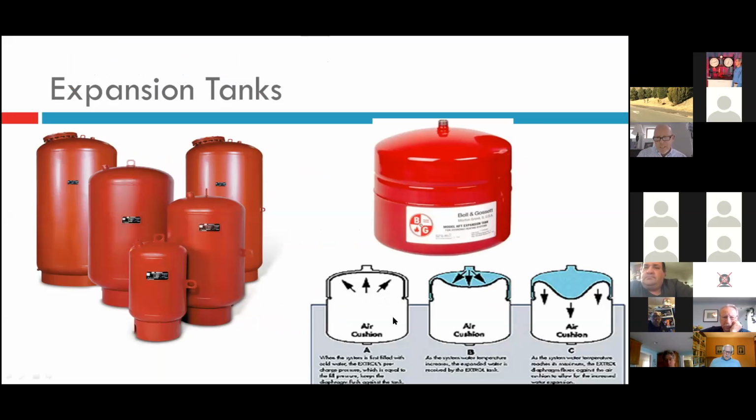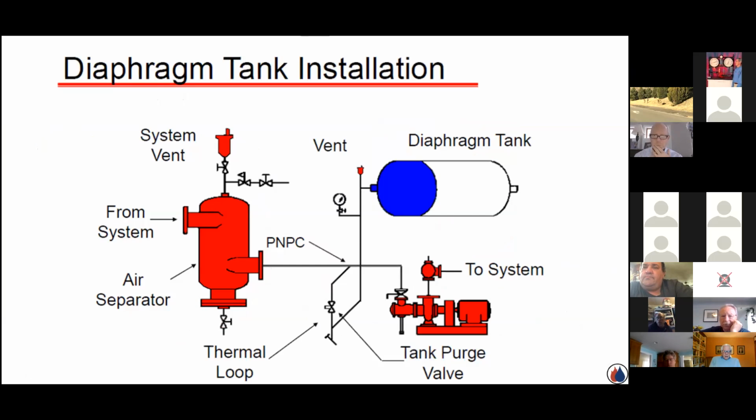What's happening here, this is a great little picture. When they're pre-charged, there is no water in them. When you attach it to a system that hasn't started the boiler, so the water's at ambient temperature, I really don't want any water in that tank, because that's how this tank is sized. It's only sized to accept water as the system water gets heated. It will enter this tank and compress that air, and the pressure will rise. But when the tanks are sized properly, that increase in pressure stays below the relief valve. We keep that system water from discharging onto the floor.